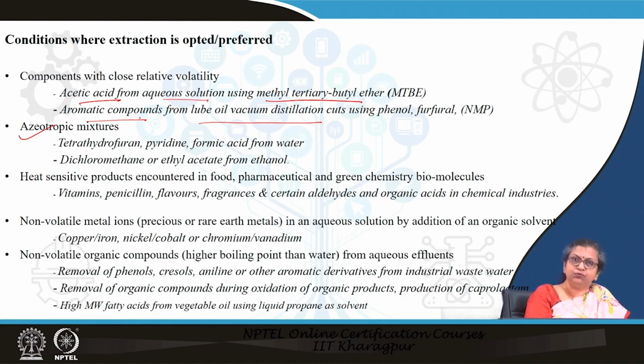There can be situations where the product that we want is very heat sensitive, and therefore we cannot go for distillation, it cannot withstand the heat which is going to be supplied in this case. This is more relevant for pharma companies, food industries, fine chemicals, particularly for the extraction of vitamins, penicillins, flavors, fragrances, etc. Also in chemical industries for recovering of certain aldehydes and organic acids.